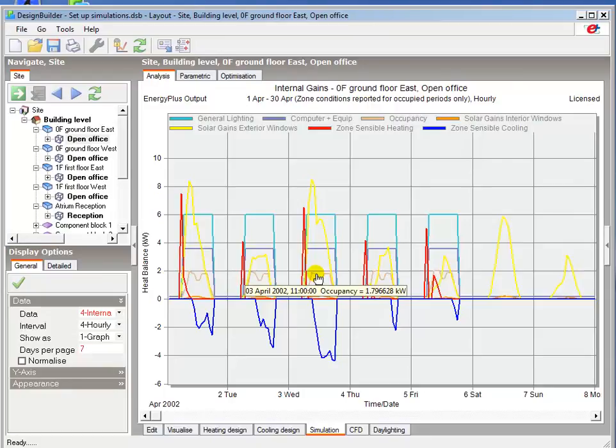The graph shows that the deadband set between heating and cooling is sufficient to prevent unstable HVAC system operation and simultaneous heating and cooling, which could have a marked impact on the predicted energy consumption and resulting CO2 emissions of the building.